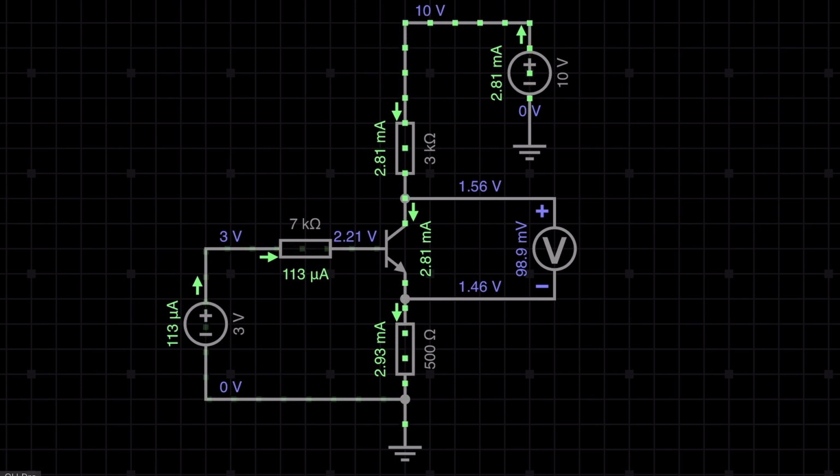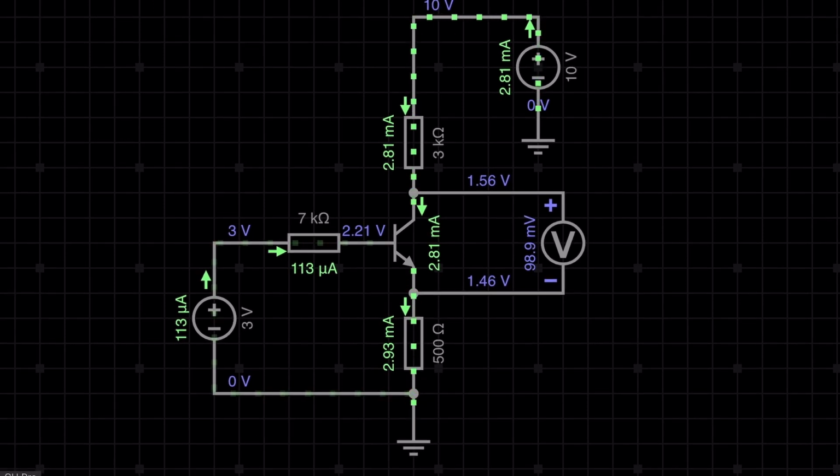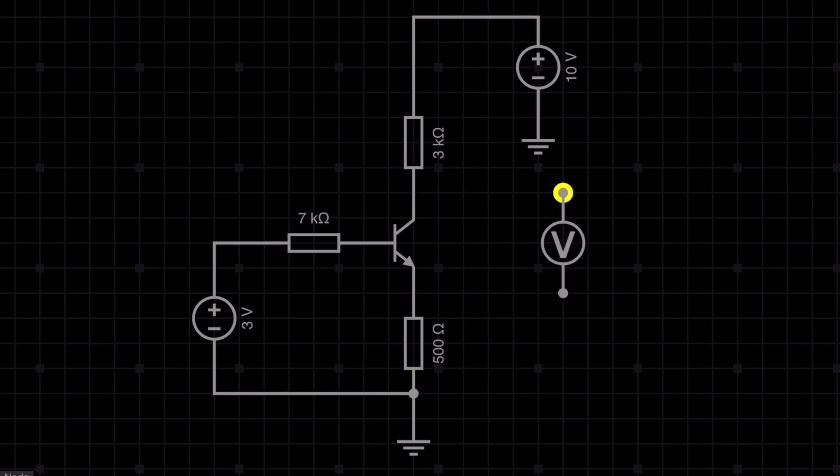From our calculation also, we got the transistor working in the saturation region, as we get VC equal to negative if we think that IC equals beta into IB. So the first question is complete. Let's go to the second question. In the second question, we already assumed that the transistor is operating in the saturation region, and we considered VC is at 0.2 and VB is at 0.8, and we calculated the value of IB and IC, and from then we calculated the value of V0.